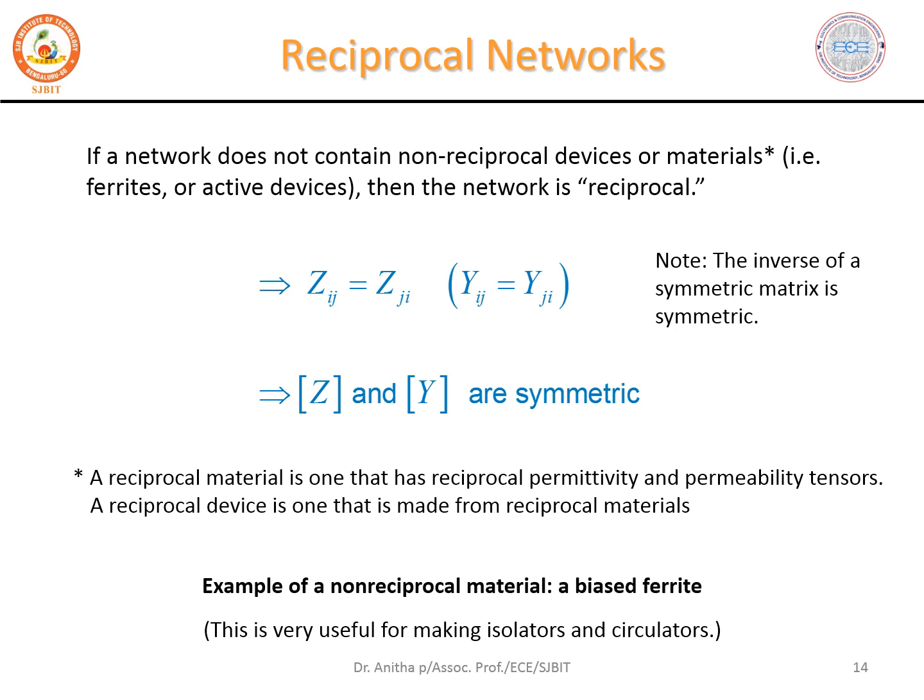Okay, in today's session we had seen the properties of the S matrix, then the losses associated with a microwave network, like insertion loss, transmission loss or attenuation, then reflection loss and return loss. Then followed by the five properties. All diagonal elements must become 0 for a matched network, and the symmetry property, Sij equals Sji. Then the unitary property, S conjugate transpose multiplied with S must be equal to the identity. Then we had seen the phase shift property: if you change the reference plane, the phase change will be accounted for.